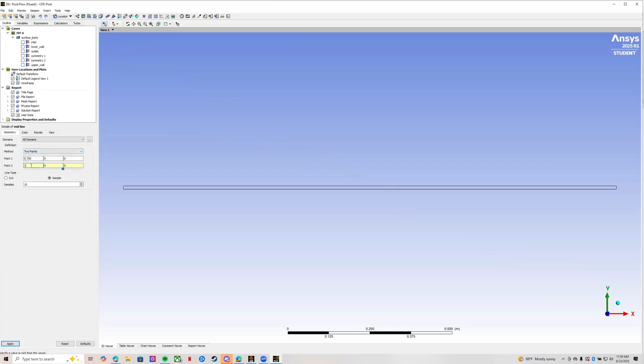So in this case, it was 1500 millimeters, so we'll be going at a section of 750 millimeters. Make sure you put it to the right height as well with 100 samples. Just get a yellow little line there. And then you're going to go ahead and repeat that for the end line. In this one, you're going to put the very edge, basically as far to it as you can. And again, make it the right height. 100 samples and apply. This will be for your graphing portion later. Next, we're going to go ahead and do the contour.